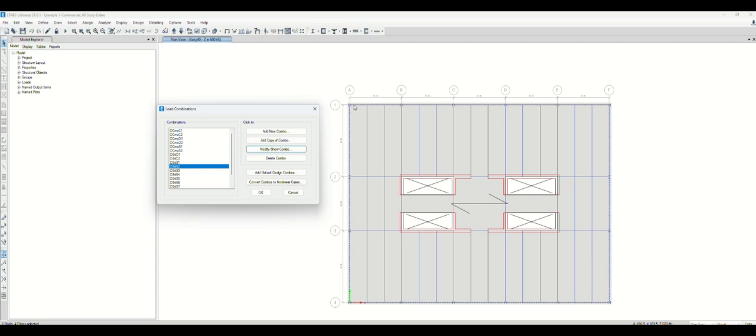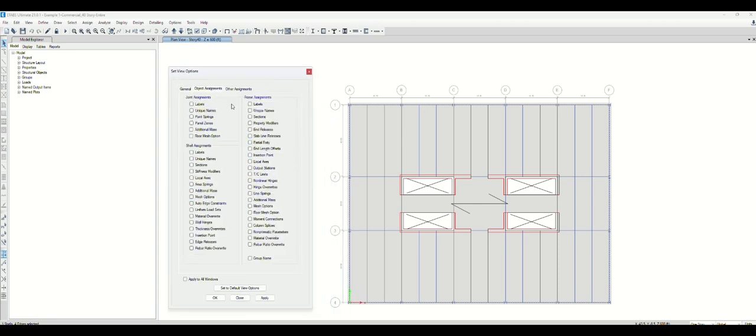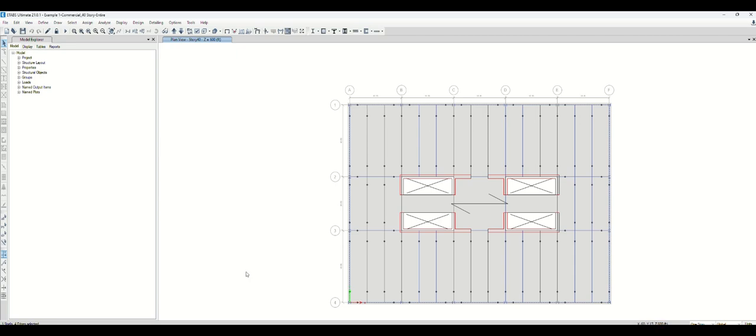For the columns, these are currently composite beam only, the gravity frame columns, which are meant to take only gravity forces, not lateral. None of the columns and beams are contributing to the lateral system because we have all the beams moment released, right? So we most likely use S1 and S2 load combinations for our column design. So let me, again, you can just double check your moment release to see that all the beams are simply connected, right? Moment release. This is simply connected to the column.